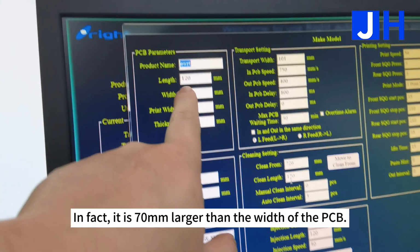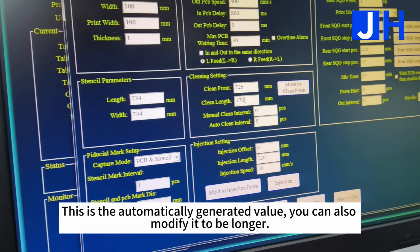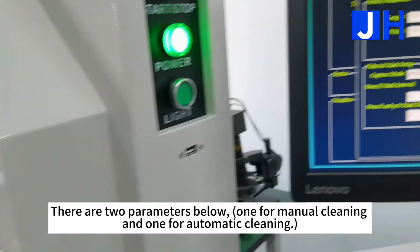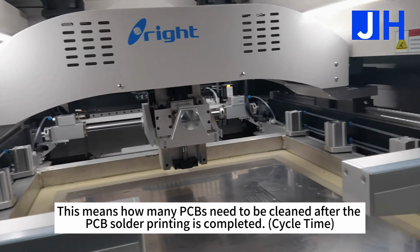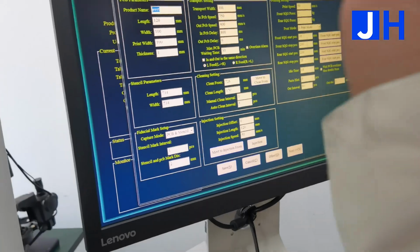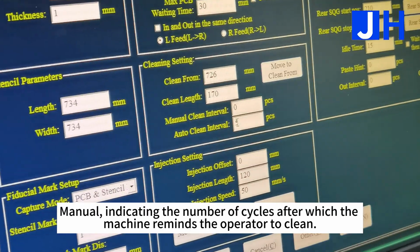In fact, it is 70 mm larger than the width of the PCB. This is the automatically generated value. You can also modify it to be longer. There are two parameters below, one for manual cleaning and one for automatic cleaning. This means how many PCBs need to be cleaned after the PCB solder printing is completed, cycle time. Manual indicates the number of cycles after which the machine reminds the operator to clean.